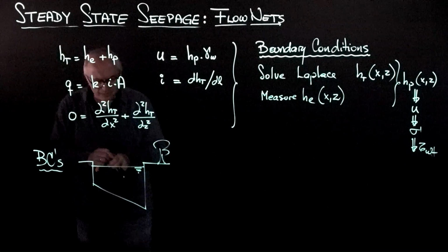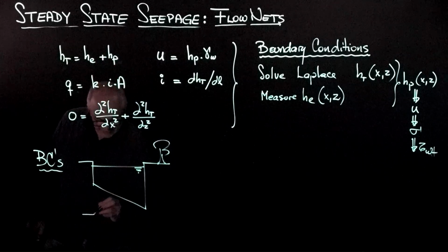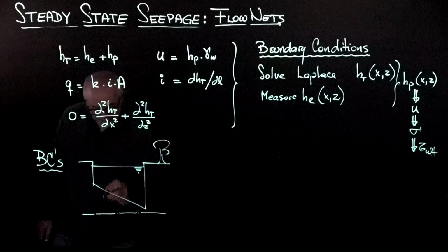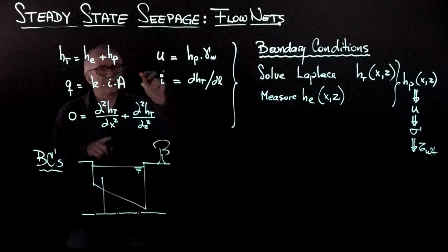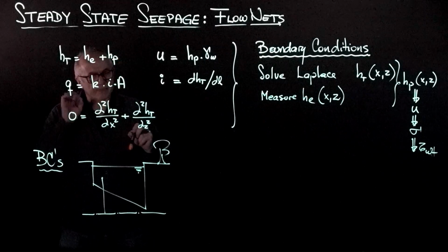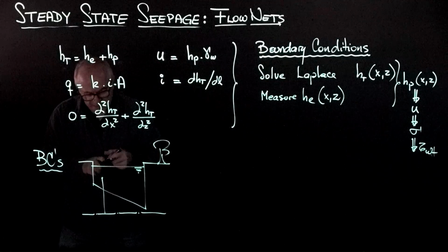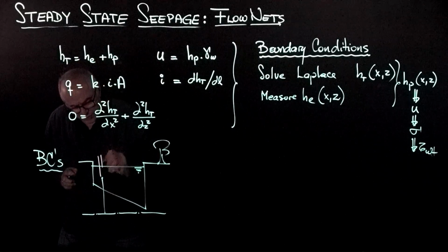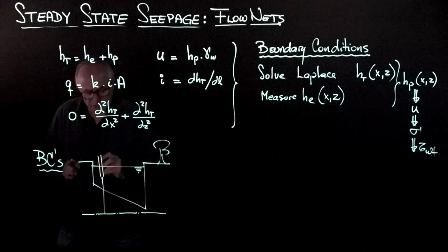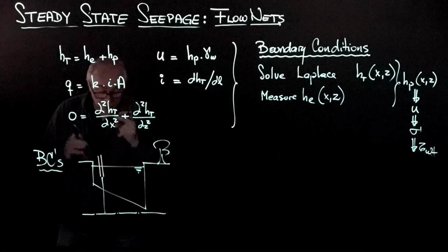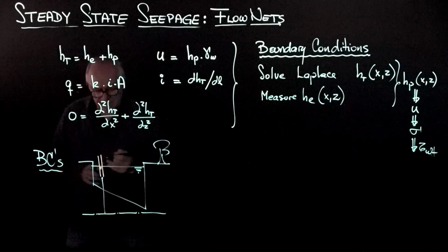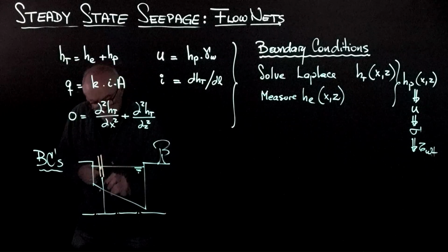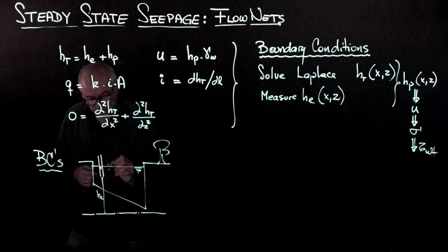Well, at any point, compared to a datum, I can check the elevation of the point, and remember, we are going to put a piezometer to get the pressure head, so at every point we can place a tube and think how high the water will rise in the tube. And because of communicating tubes, the water will rise in the tube as much as it is on the outside. Therefore, this will be the H elevation of the point, and this is the H pressure at the point.